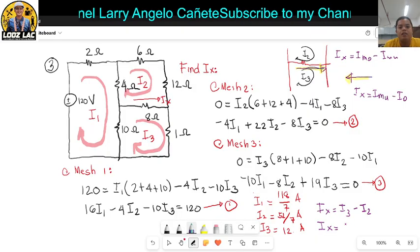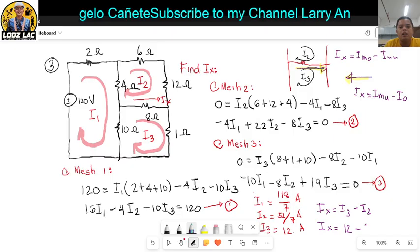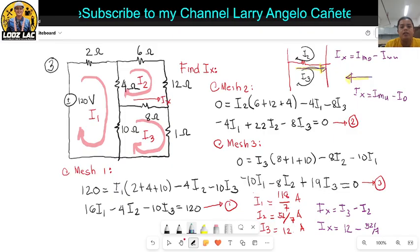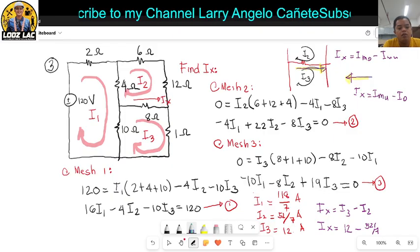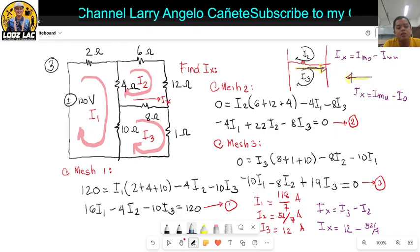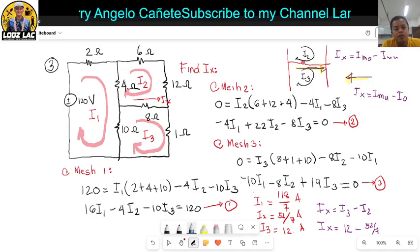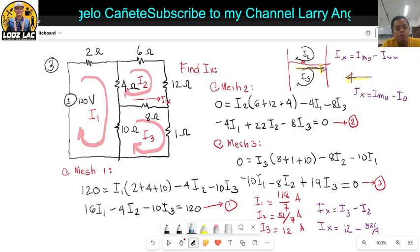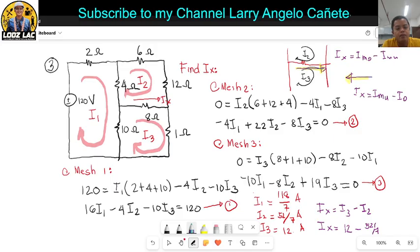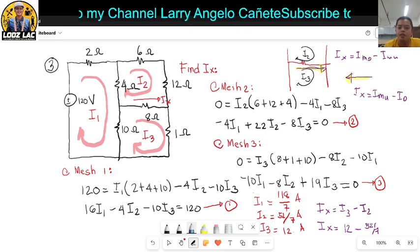If it is positive, the direction of current is correct. So your Ix here is 12 minus 52 over 7. Assuming wala tayong mali sa calculator side in solving for the three equations, we subtract 12 minus 52 over 7. So more or less 32 over 7.